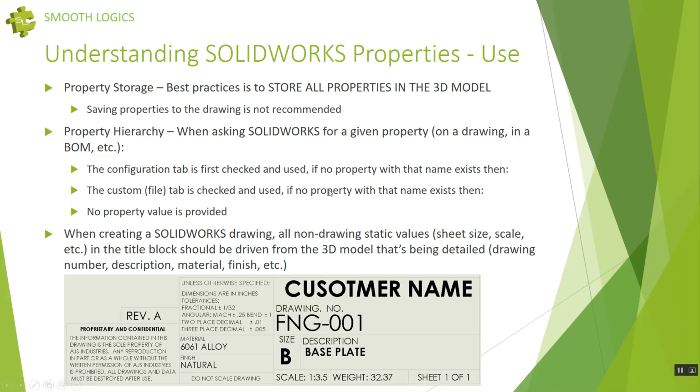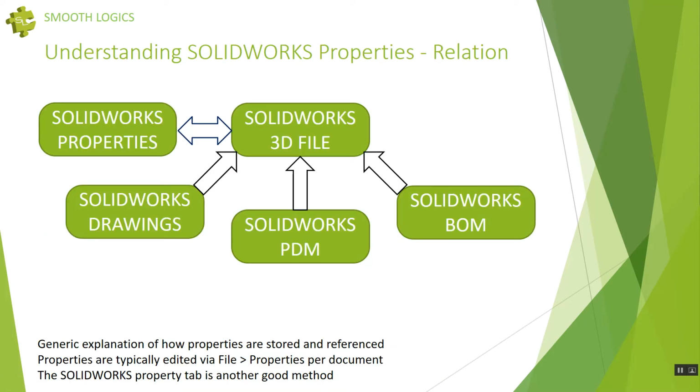So let's see what I'm supposed to be doing next in my PowerPoint. Oh yeah, okay, so no properties on drawings, that's bad. Properties on models, that's good. So here's how the property structure works. The properties are pretty much always stored in the SOLIDWORKS 3D model. So we have SOLIDWORKS properties that can be influenced by that 3D model. The SOLIDWORKS drawings point to the SOLIDWORKS 3D model and get their properties, SOLIDWORKS PDM, SOLIDWORKS BOMs, etc.